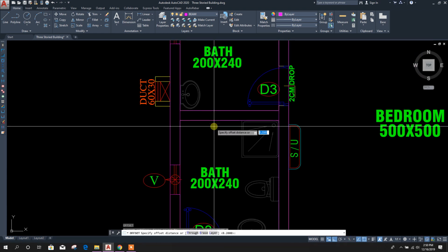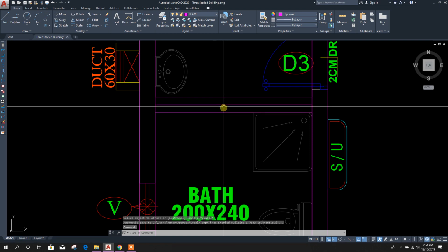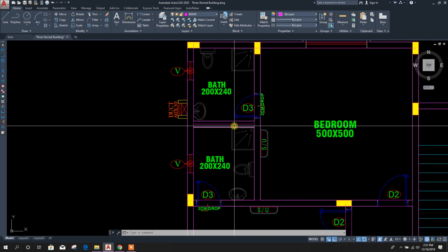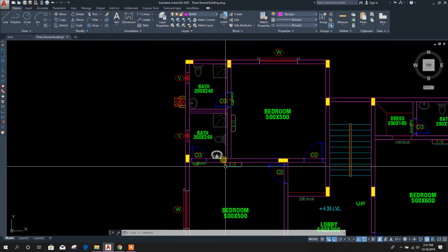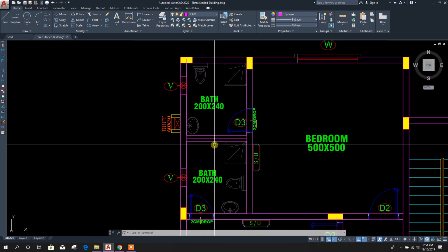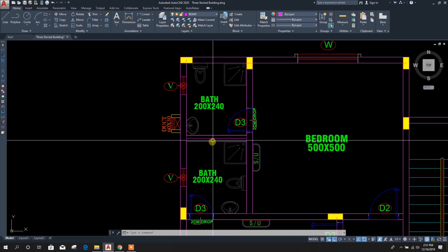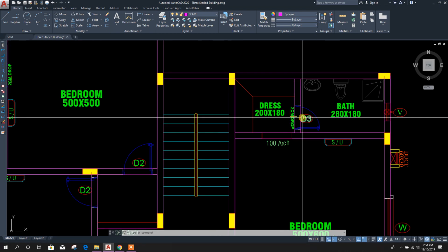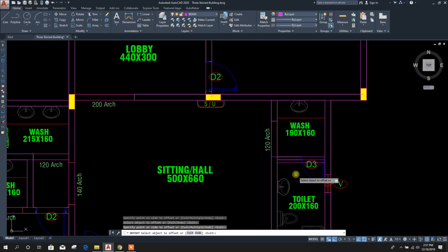If we provide extra rebar like this, 0.1, like this, 3 Y 14 or 16 millimeter diameter bar at top and bottom for providing more stiffness to hold the wall. Usually we follow this provision to consider this as a full slab, and inside this full slab there will be extra bar. Same here we will do 0.1, here also we will do.